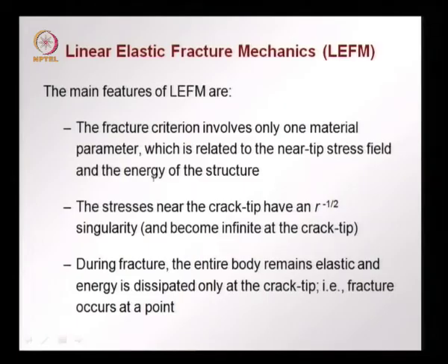During fracture we assume that the entire body remains elastic, and whatever energy is dissipated during fracture occurs only at the crack tip, that is, fracture occurs at a point which is the crack tip. These are the main features of linear elastic fracture mechanics, and these have limitations, they cannot be applied to all materials and all situations.